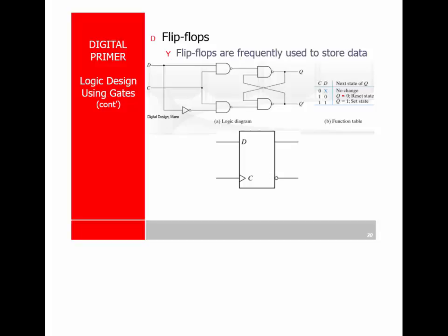A clocked flip-flop will only transition on a rising or trailing edge of the clock. This one here transitions at any point, but we're assuming that we don't change between clock cycles. But since they put the little triangle there, that means that's a clocked input.